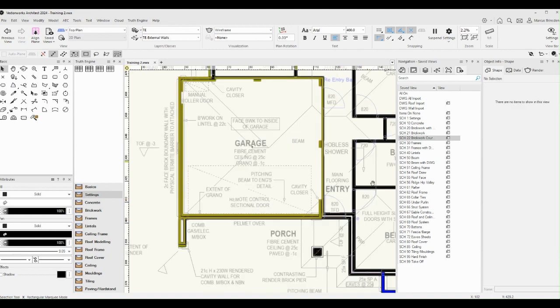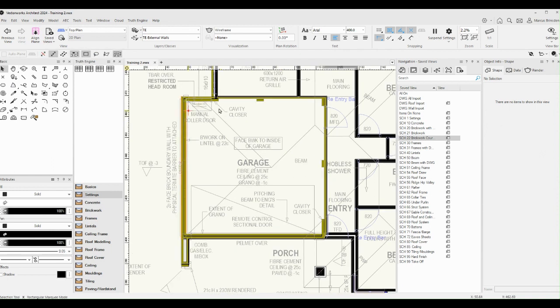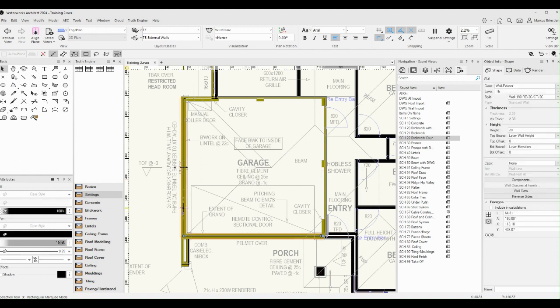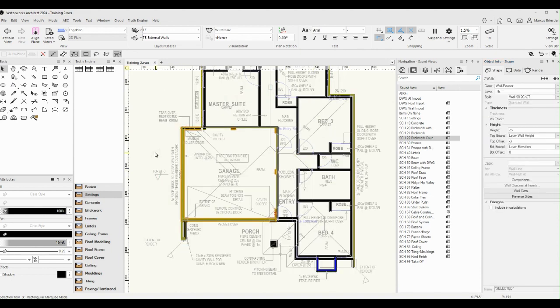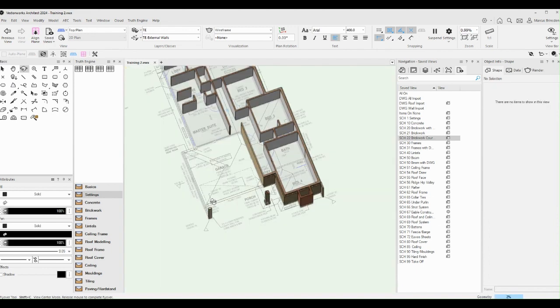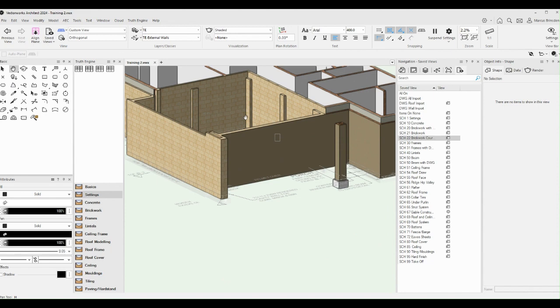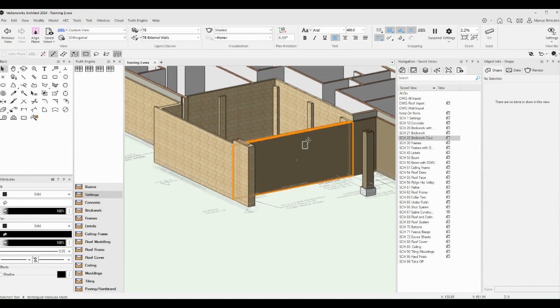Okay, let's start by changing all of these garage walls to 25 courses. So we have a 25 course ceiling throughout here. So I'll select those walls that we need to change. Okay, so all of those walls I've selected are currently at 28, but I'm going to make them 25 courses. A bit of a think. There we go, that's done. So now if we zoom out a bit, those attached piers, the front wall and the boundary wall have all been dropped down 3 courses.